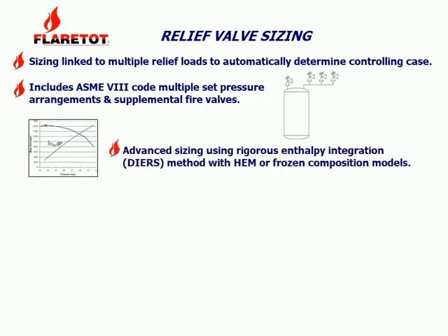The Dyer's method is provided to size the relief valves. This consists of a rigorous integration of the momentum balance equations, in conjunction with the physical property simulator. It is suitable for two-phase sizing, but you should note that the underlying equations apply to all phase states.